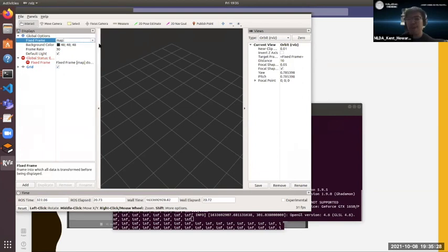We don't have a map because I didn't load a map, but we have our robot odometry that we can use as the anchor point for now. So this fixes the global status. And later on, when you're working with your own RViz, you need to do this. So remember, change the fixed frame from map to odom.